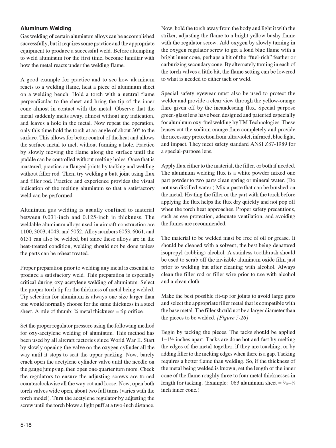Make the best possible fit up for joints to avoid large gaps and select the appropriate filler metal that is compatible with the base metal. The filler should not be a larger diameter than the pieces to be welded. Figure 526, begin by tacking the pieces. The tacks should be applied 1 to 1-1/2 inches apart.